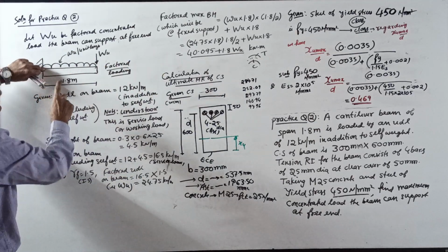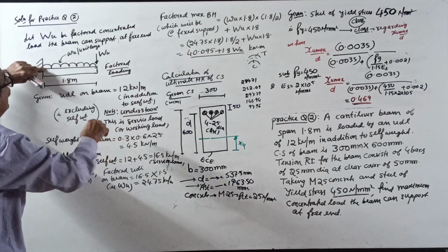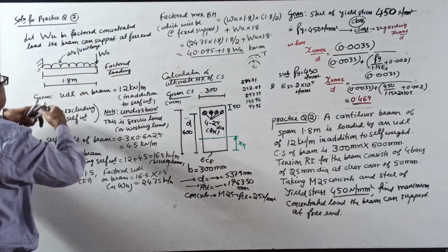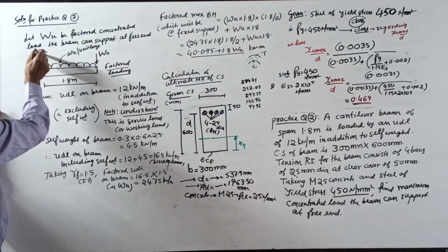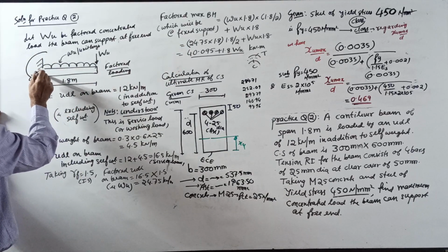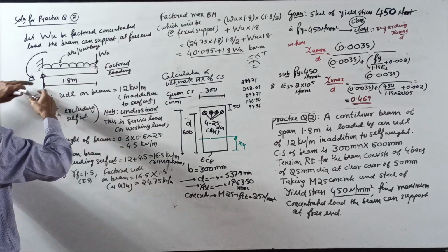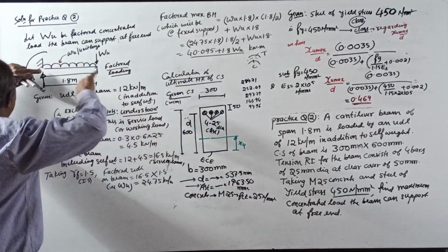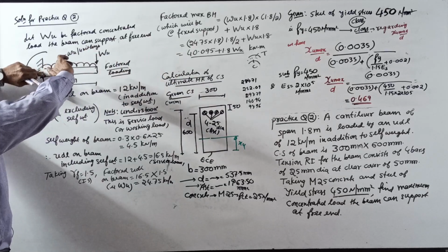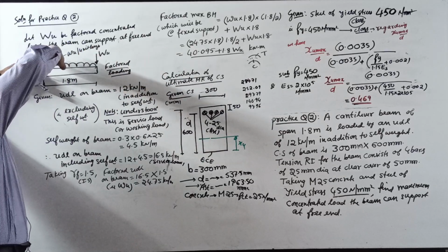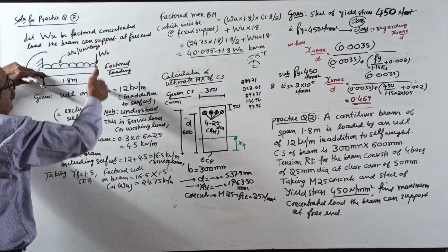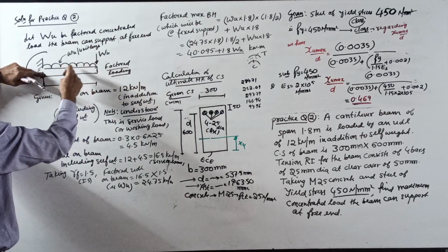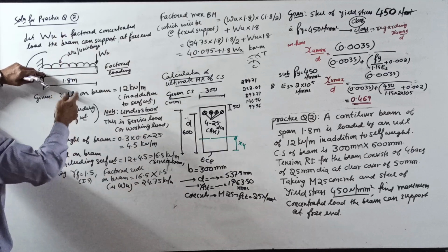What you have to do is, don't use a formula for the cantilever. See how much the BM is, looking from this side. At the fixed end there will be a reacting moment and vertical reaction, which are not required. Go to my class on the SFD BMD series. So here, bending moment, find directly: WU into 1.8 into 1.8 by 2, and small w into 1.8.